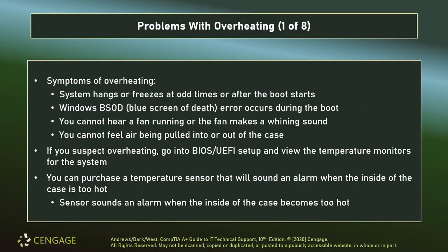Overheating, of course, has a ton of different signs. Blue screen, visibly hot to the touch. Sometimes you can see a little bit of a heat ripple coming off when it's really, really hot. You can see the fan, especially if it's in a cooler room. You can touch it, things like that. Sometimes you'll smell that hot, burnt dust smell. Not necessarily that something got scorched, but just that you haven't turned on your heater all winter, and then here it comes, and now everything smells slightly toasted.